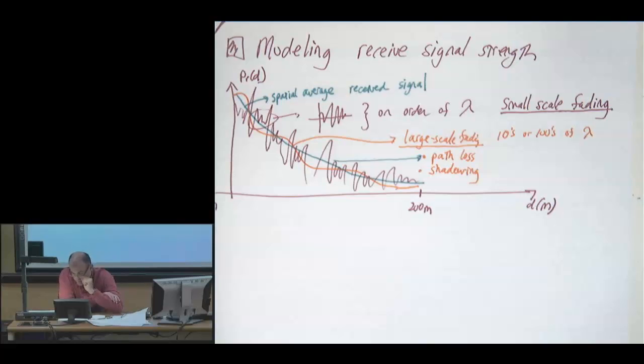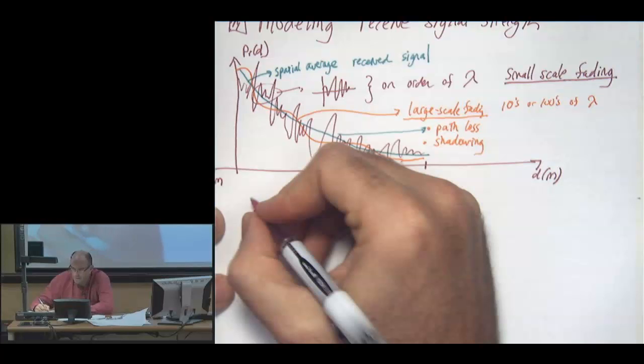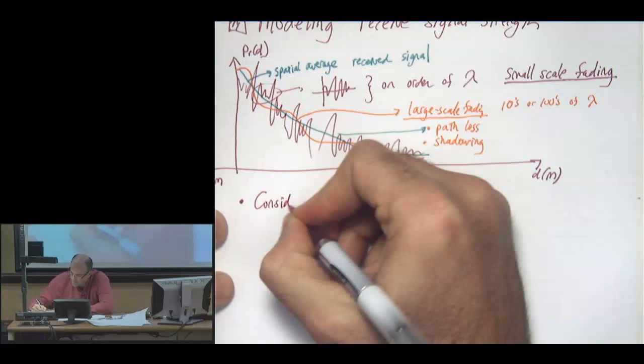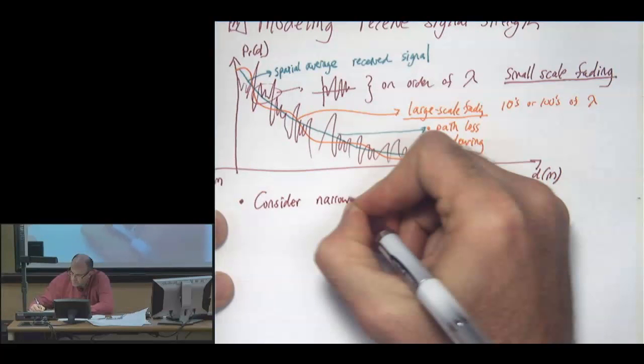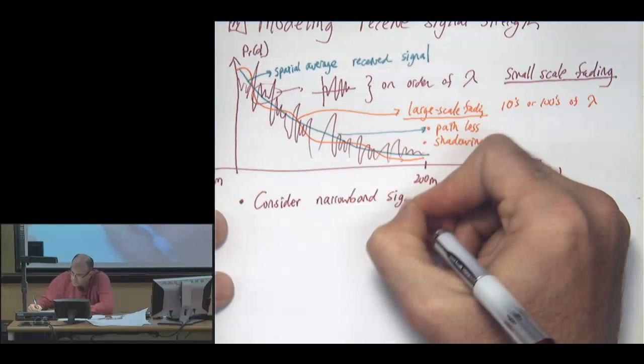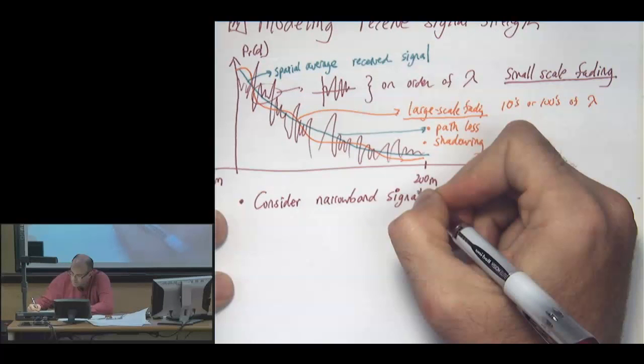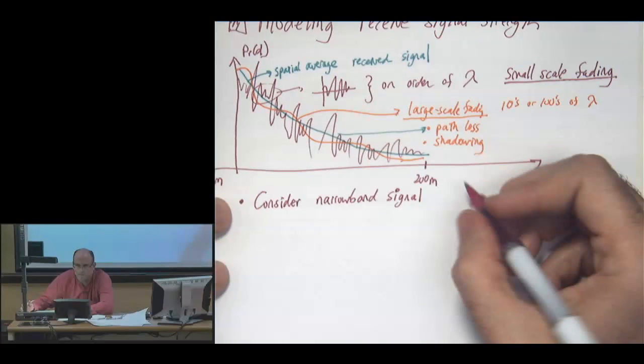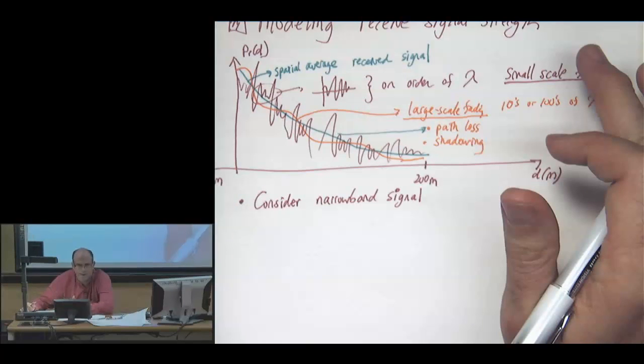Okay, so now let's look at coming up with a received signal model here that will capture some of these effects. For the purposes here, we're going to consider a narrowband characterization. So for now, a narrowband signal, where this will make more sense, but essentially there's no intersymbol interference effect. So it's just like sending a single carrier, let's say.